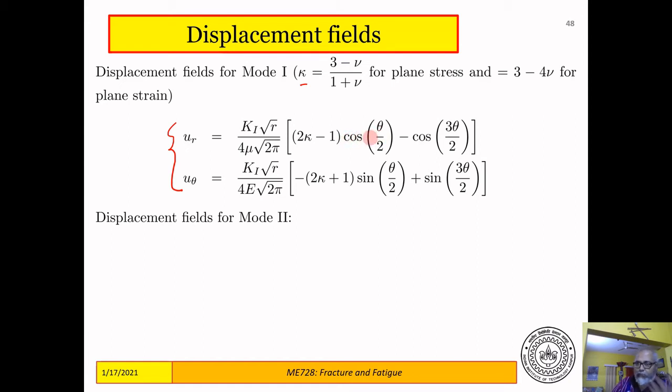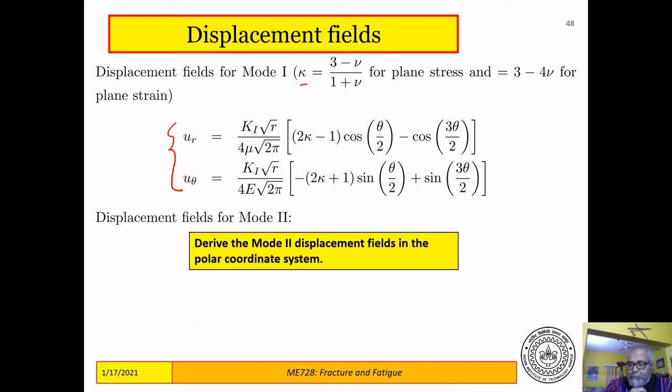The stresses don't care about plane stress or plane strain. They're the same in plane stress or plane strain, but the displacements depend on your choice of approximation. The displacement fields for mode 2, I leave that as an exercise, and I'll put it in one of the assignment sheets. You can start from the stresses in mode 2, get the strains using the constitutive equations, and integrate them to get the displacements. So I leave that as an exercise for you.